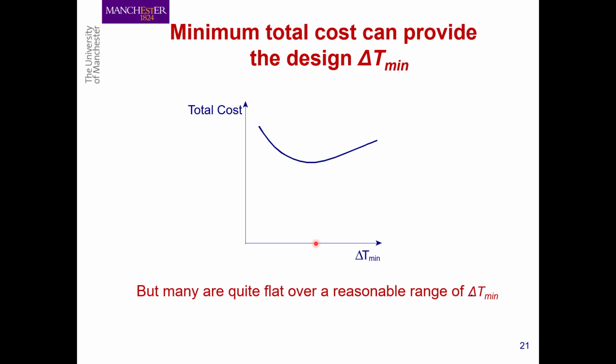Also, you do, for example, sensitivity analysis and inflation analysis to see the likelihood of changing the cost of energy over that period. For example, is there a possibility of having renewable energy, or do you have to stay and use fossil fuels? So you predict all these things, and then based on all these estimates, you select an optimum value of delta T min.